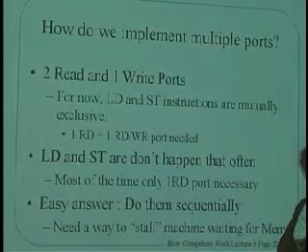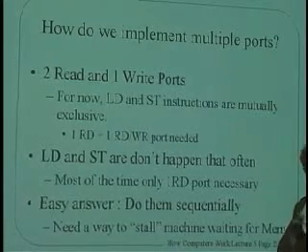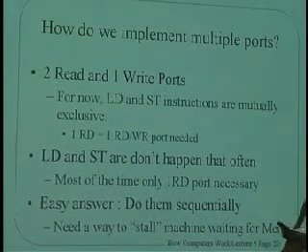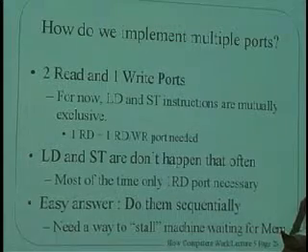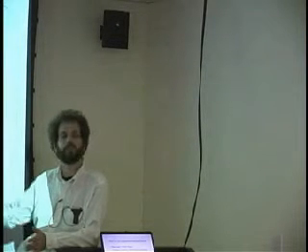And if it ever happens that we need to do a load and a store, instead of trying to build a memory with 2 ports on it, or God forbid 3 ports on it, and have the expense of these 3 expensive ports all the time, when we're really only using one most of the time, if we ever need to do a load and store, we're going to hiccup. We're going to say, well, wait a minute. We're trying to do a load or a store. Don't fetch a new instruction to do. Instead, stall, and wait for the next cycle and insert an extra hiccup. And during that middle cycle of stall, use the one port that we used to use for doing reads and use it to execute the load or the store.